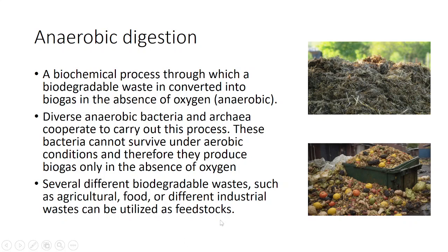There are different kinds of biodegradable wastes which can be used for this process. Of course, your feedstock should be biodegradable. For example, you cannot use some non-degradable matter to produce biogas, especially under anaerobic conditions, because some feedstocks are degradable, but they are not degradable under anaerobic conditions. So you have to study your feedstock in detail.